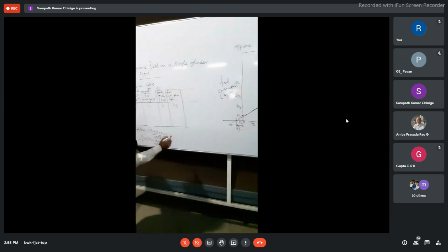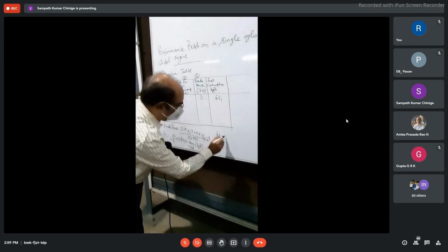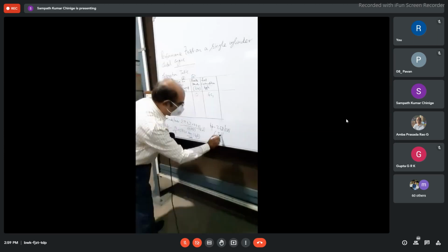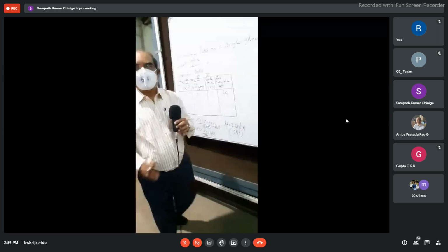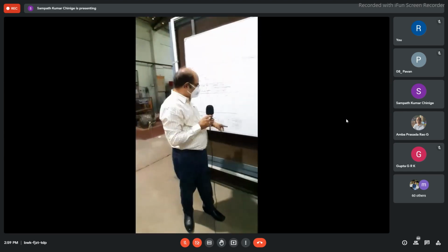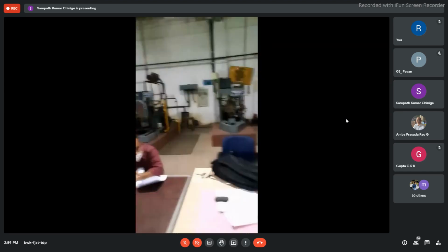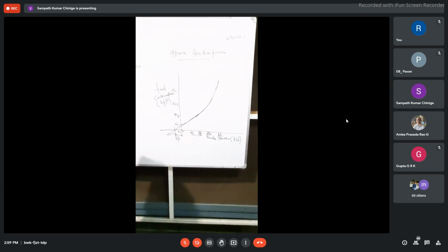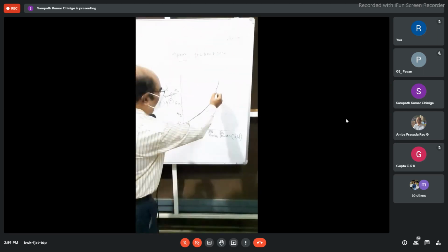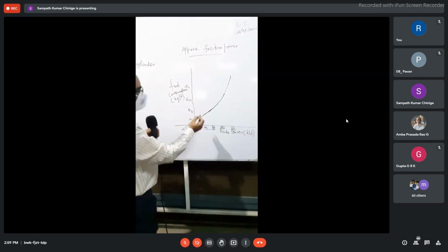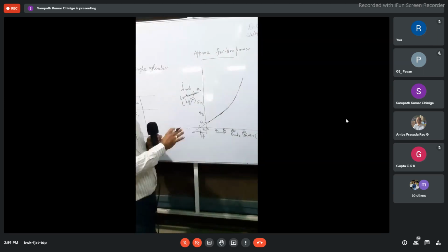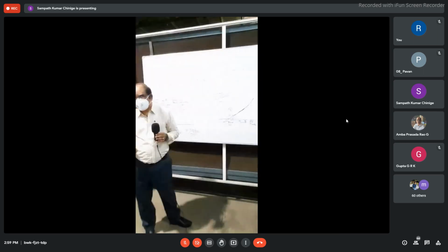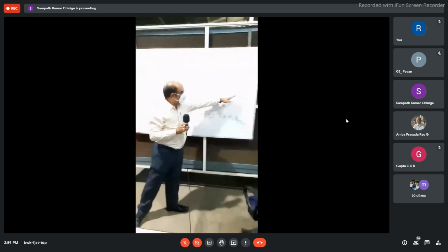So this maximum power or rated power is equal to 3.68 kilowatts, corresponding to the 5 HP shown on the nameplate details of an engine. What is 75% of the 3.68? Somewhere you may get it here. So if you draw a tangent at that point, it almost cuts like this. Suppose you draw a tangent somewhere here, this method is very sensitive to the drawing of a tangent. Instead of drawing a tangent, what we are trying to do is extend the linear portion of the curve.